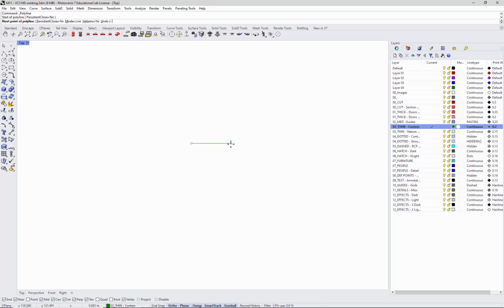And draw a line, and 0.25 is going to be in inches. And then I hit the space bar to stop that. And then I could draw another line vertically, but I tend to like to use editing commands. So I'm going to use mirror, MI as the shortcut, and I'm just going to mirror this guy at a 45-degree angle so it splits in half.